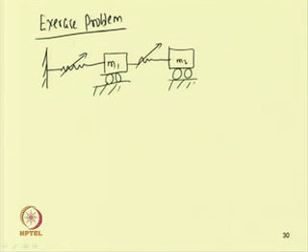So, this K1 can be taken as K1 x1, and this is x2. So, here one can take K1 x1 plus K2 x cubed, a cubic nonlinearity. Here also one can take this cubic nonlinearity, and one can write this equation using this K2.